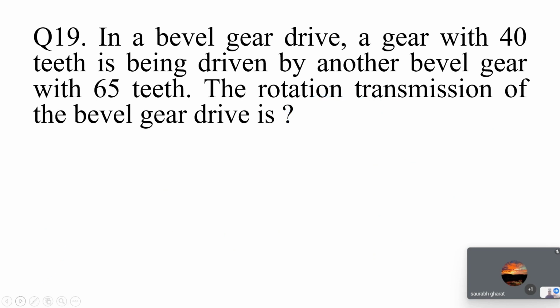So exactly like that, we have checked the question. But here is a twist. You can see a gear with 40 teeth is driven, and your driver is bigger, with 65 teeth. So your speed must increase here. It will be more than one. I need to take the ratio only, but it's more than one. That's how we need to solve it.